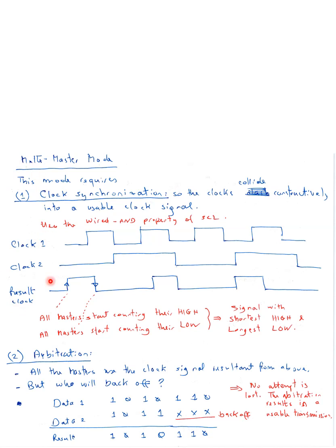So summary of this is, if two masters collide the clock, they're gonna work out correctly. One of them will back off once they start differing by a bit. So a couple of cases you can think about is, it seems that if you try to communicate to a lower address, then you have preference, because here you can see the lower address will prevail, right? So the master communicating with a lower address probably will have preference, will have higher priority. This is considered just a randomized feature, so we're not giving too much attention to this.